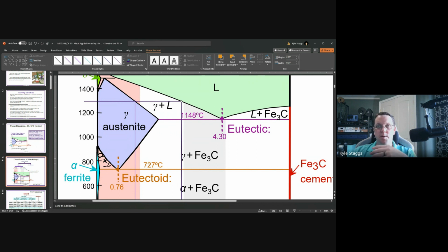So a lot of the heat treatment questions were highlighting that these temperatures are specific to a specific region. So they're very key. In order to reach liquid, you have to be above 1148. Above 1148, for sure, you have liquid in your composition, period.